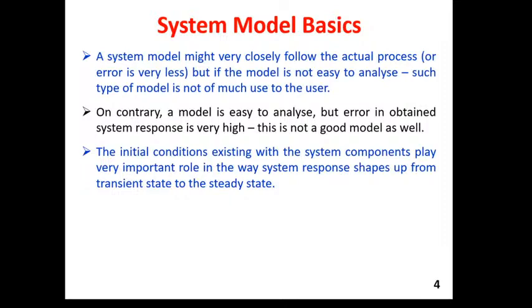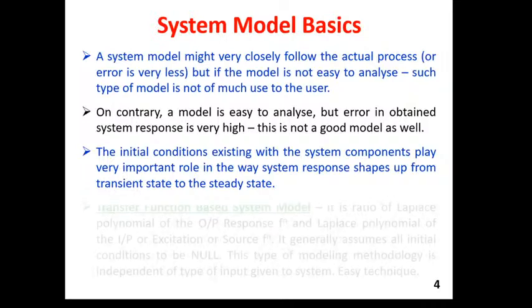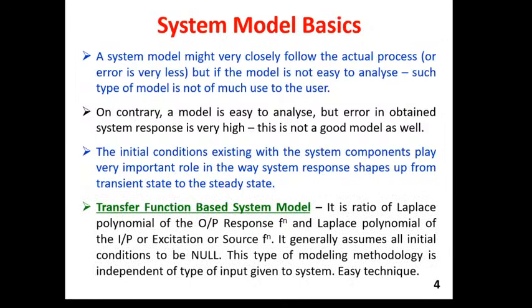We will see towards the end that the combined system response has two parts, one called the zero input response and one called the zero state response. It is very important to know that the zero input response actually culminates in the transient behavior of the system, and the zero state response goes towards the steady state response of the system. So the initial conditions, or initial energy stored in the system, are responsible for the transient or initial part of the response of any system. Hence, initial conditions play a very important role in the overall system response.